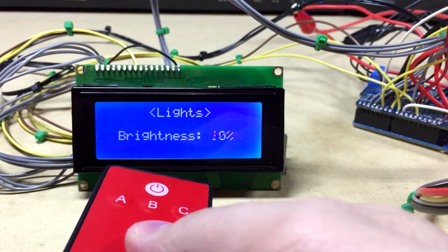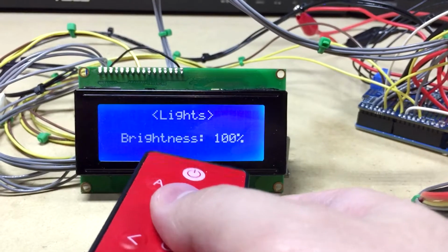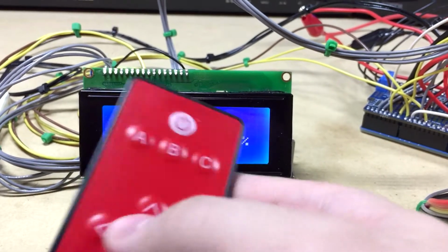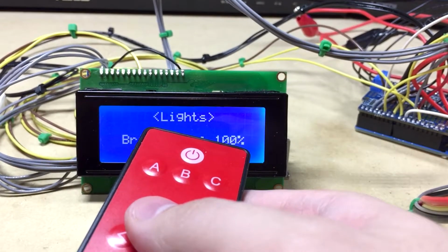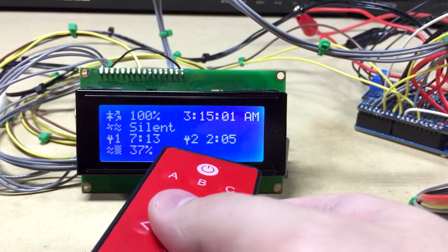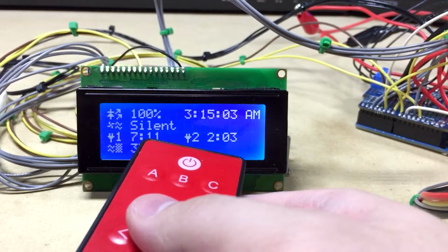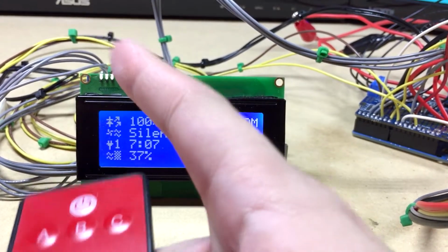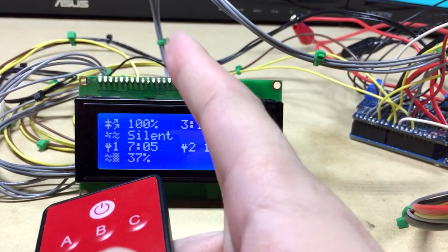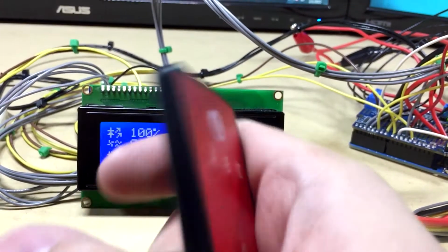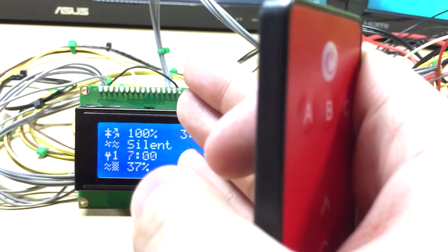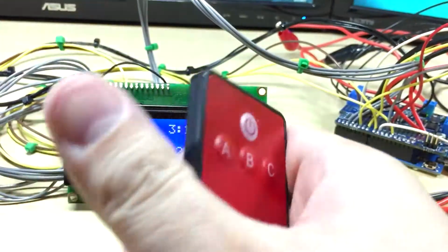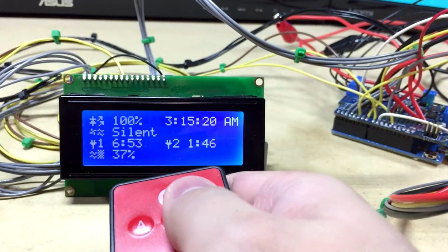But that algorithm would be super simple if I had all four strings fading on and off together. But to get a better range of lighting, I have each string turn on one at a time. So when you hit 25%, the first light string is at 100%. When you hit 50%, the second light string is all the way up. And then when you start going above 50%, that third string starts to turn on. And so that was what made it tough.